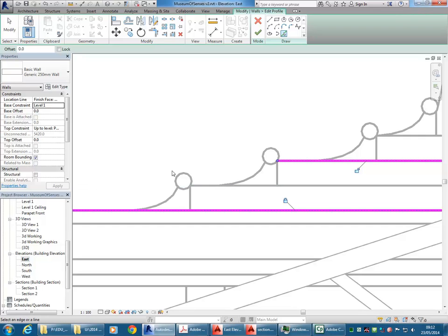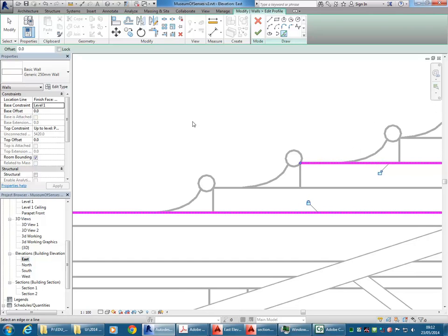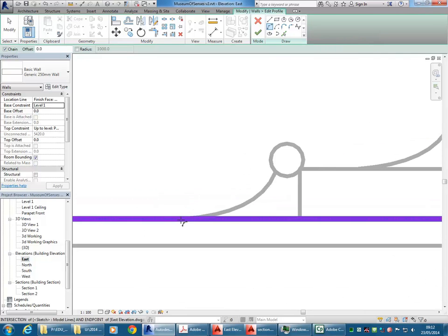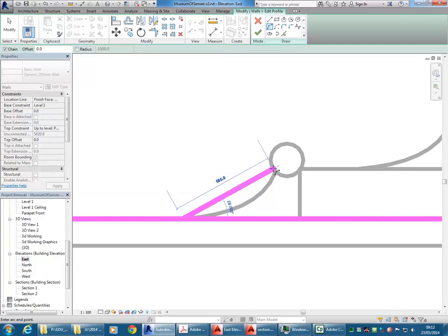Actually, it's not highlighting it, and I know why. It's because this came from Illustrator, so those all would be a spline. Normally, even curved things won't be a problem to pick if they come from AutoCAD. So anyhow, it's fine just to trace them. Using the Arc tool, I'm going to trace that shape, and you can see it's actually snapping to it then. I might need a couple of arcs here, but I'll see if I can do it with one. That'd be good.